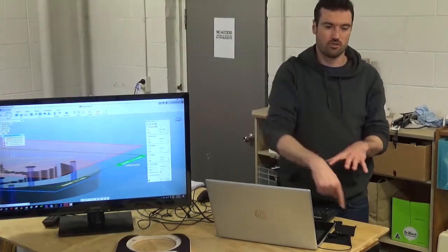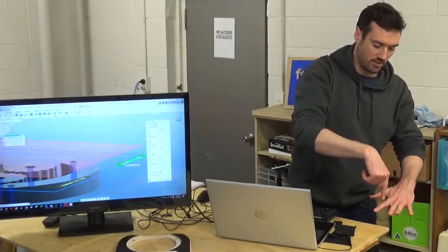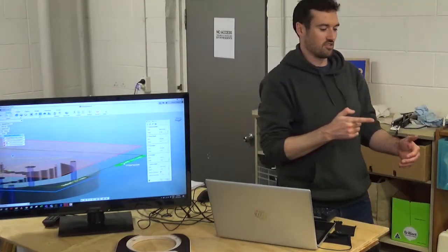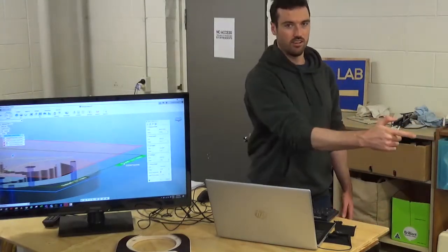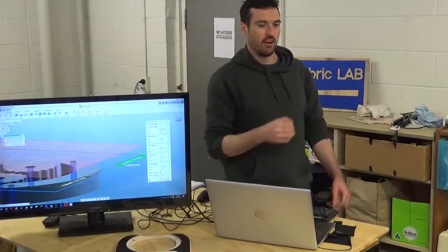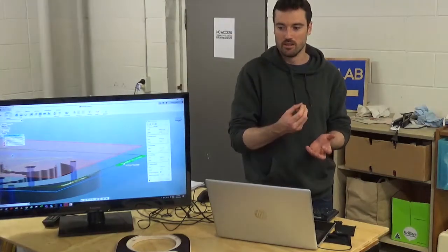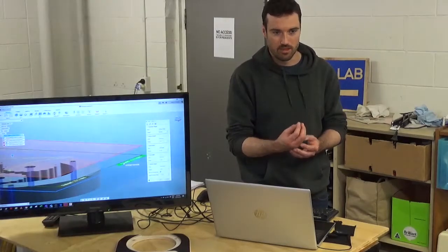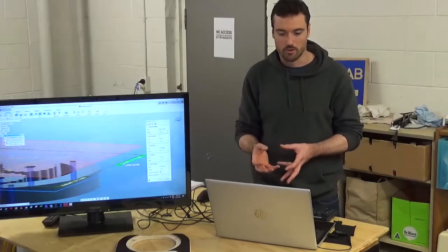So when you're doing a drill, what we're going to do is called peck drilling. It drills a little bit in and then comes out. When you're drilling something, you shouldn't just keep drilling the whole way through. You should drill, pull out, drill, pull out, and that helps clear out all the material and keeps the drill cool. Because if you heat tools up too much, they soften and go blunt really quickly. So temperature control is actually quite important.